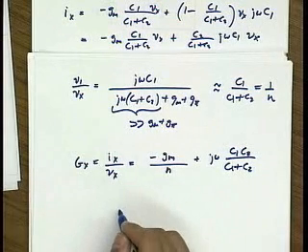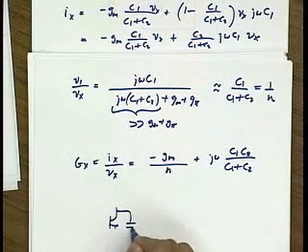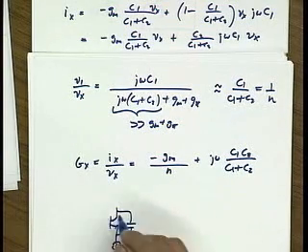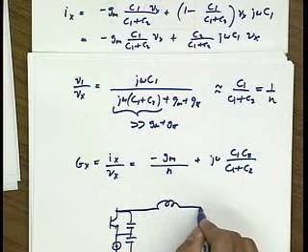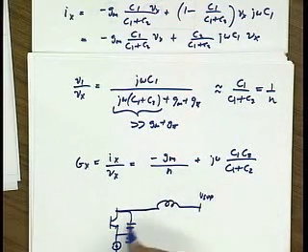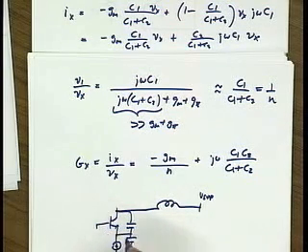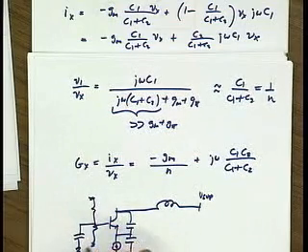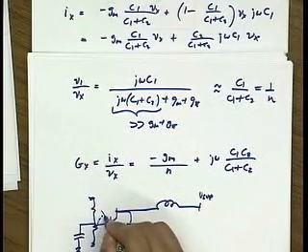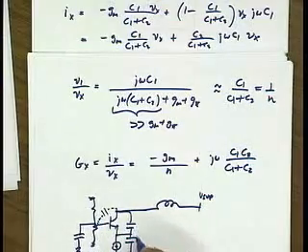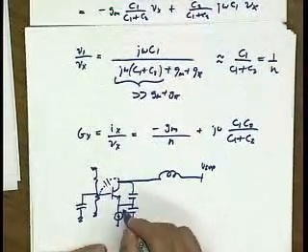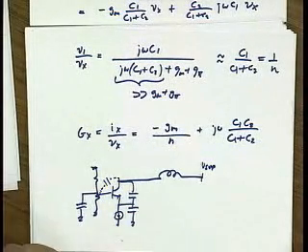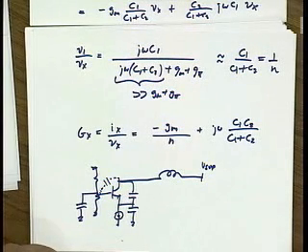Okay. So now it's very clear how we would design this Colpitts oscillator based on these equations. Let's say I bias this up. I can now use my inductor to tune out basically C mu. So this is a bypass capacitor. This inductor is tuning out C mu. It's tuning out this in series with this, where this includes the transistor parasitics. And it turns out that this is a really nice oscillator. You can make it work at really high frequencies.